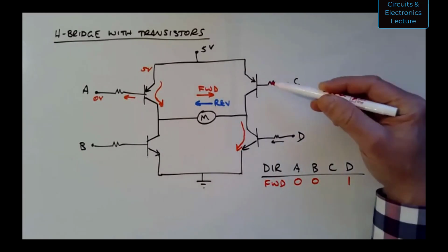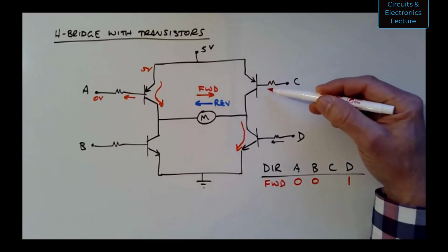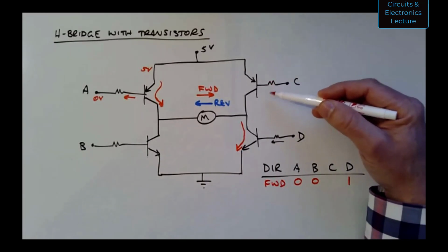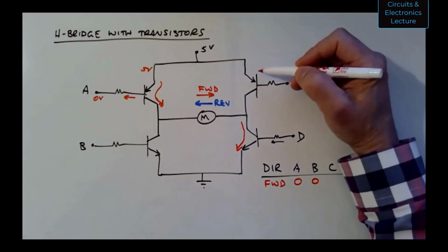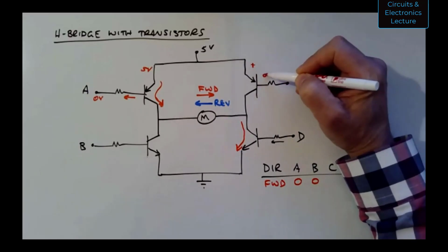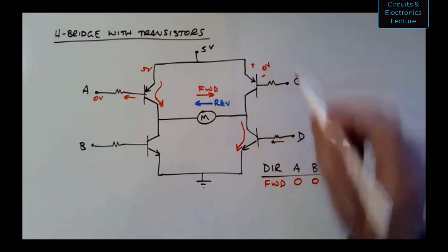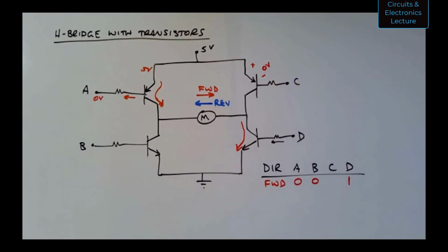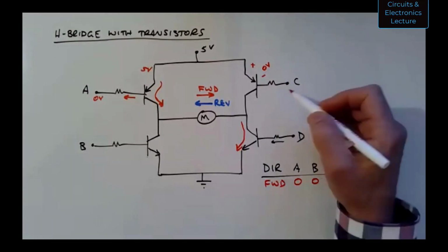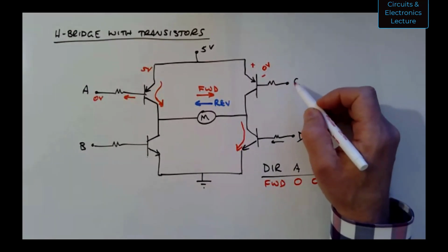C over here, we want this transistor to be off, or in cutoff. And so I want this voltage here to be 0 volts. I want that base-to-emitter junction to be 0 volts. And so how do I do that?